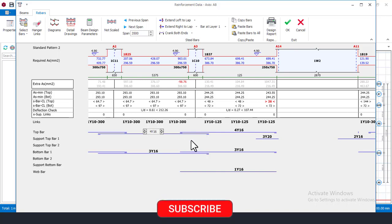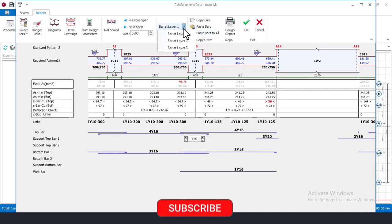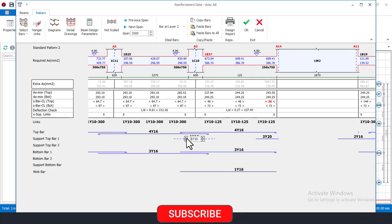So I'll come again right now and then click on this. Now, even when I'm trying to save the client's money, I also put the safety of the structure into consideration. So that's what I'm doing right now. I will use this right now and then add layer 2 at this support here, which is what the supporting bars for the top bars here at the support. And I'll come here and make it to be 2. Okay, so right now we have 4 bars at layer 1 and then 2 just at the support here.